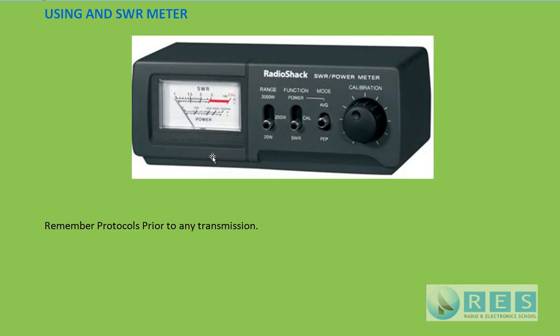So assuming you've done protocols prior to transmission and your SWR meter is connected between your transmitter and your antenna, your next step is to move this switch to the calibrate position. That's CAL. So we've moved this switch to the calibrate position.